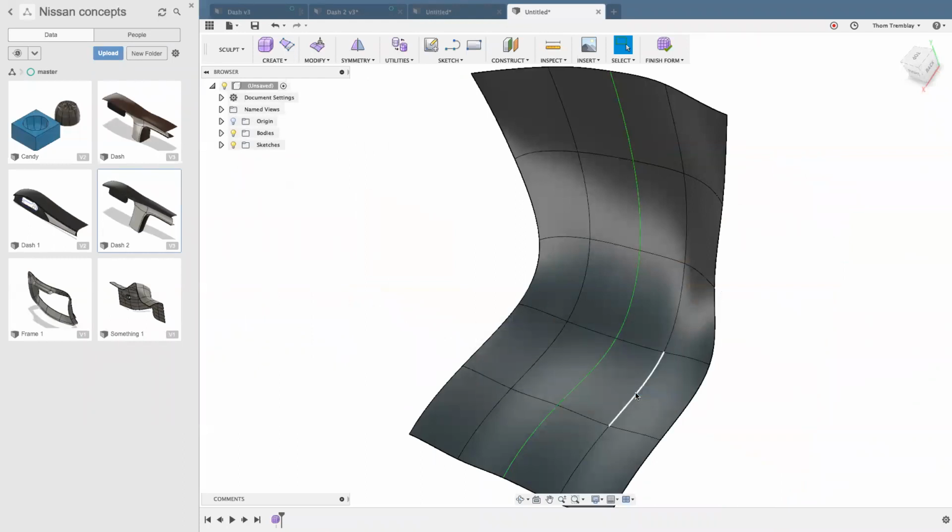Well, there's some times where that solid geometry just works. Taking an object and just extruding it, adding some fillets. In fact, what I often recommend is not necessarily allowing every edge to remain smooth with the continuity on it in the freeform mode. Because in solid modeling, you have the opportunity to create precise fillets very easily, very quickly. There are just times where it works better. And okay, back from the original discussion, there are also techniques that when you start with a solid, you can do things like converting faces and then doing replace face, which I'd like to get to, which I definitely want to show.